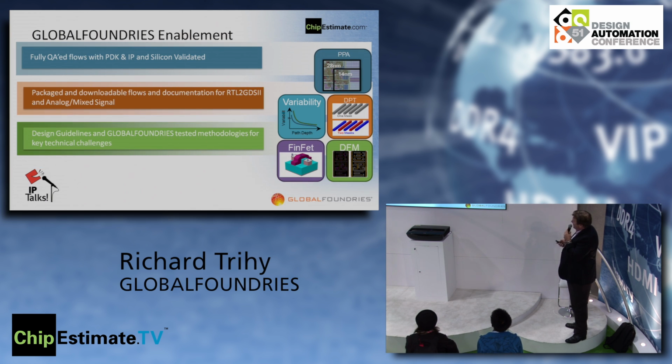So then, if I summarize on the enablement front, there's three things we're doing here. So one is we're fully QAing the EDA flows with GlobalFoundries PDK and our open source and silicon validated IP. Okay. The second thing is we provide packaged and downloadable flows and documentation for RTL GDS2 as well as analog mixed signal. So the customer can download these, you install them with our PDK, and then you have an entire flow. And then the third one is design guidelines and GlobalFoundries tested methodologies that demonstrate solutions for the key technical challenges. All of this is available for download.